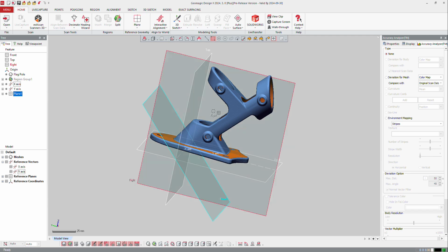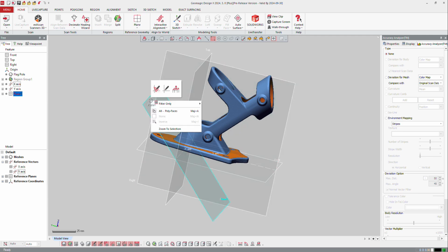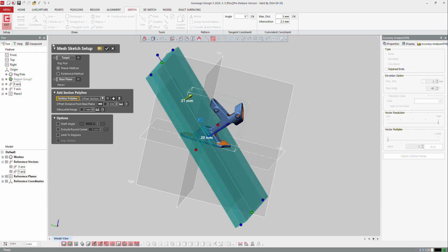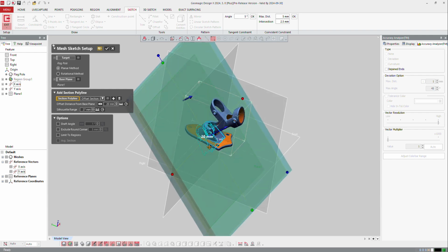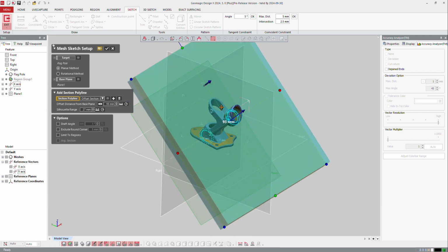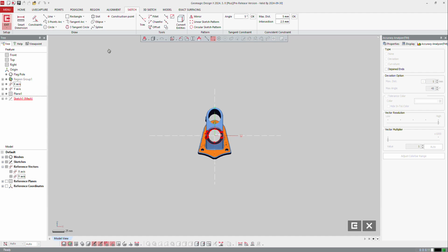file, and I can start with that shape, which is a standard shape. I will make a sketch here on the part and move it up just to get the global shape of that part. If you want, you can ask for silhouette, but I don't want to get that outside, so I will move it up. Okay, just to get the cylinder here. And okay.